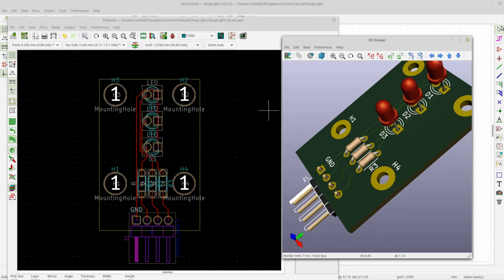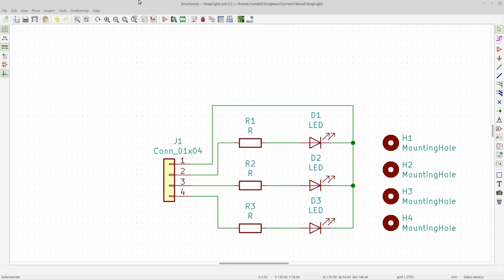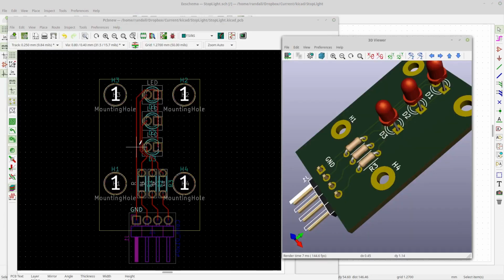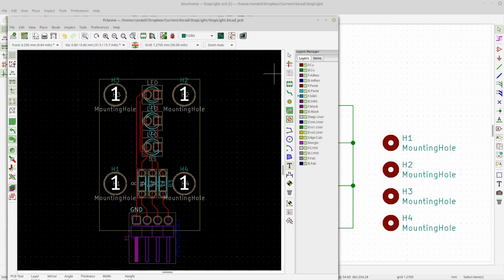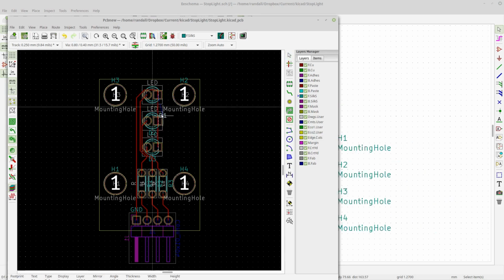Sorry, I keep saying it's over. So, oops, sorry. A little misclick there. So let's get back into PCB view. So you can move these texts around. Sorry, I keep picking the wrong thing. It's this select tool. You can move these around by selecting just the reference. So you see value of LED D2 or D1. So now when I hit move, it's just that text, and it snaps to the grid just like anything else would.